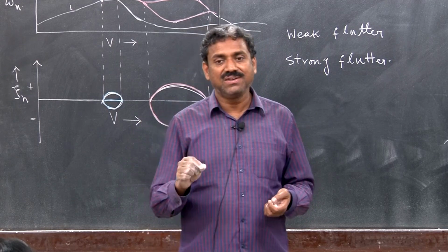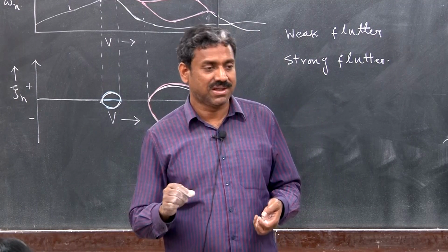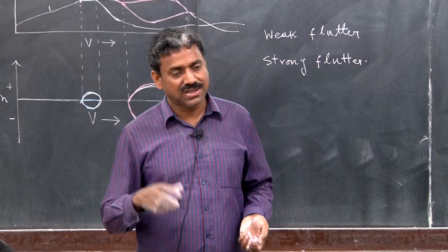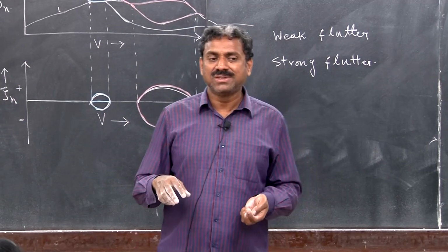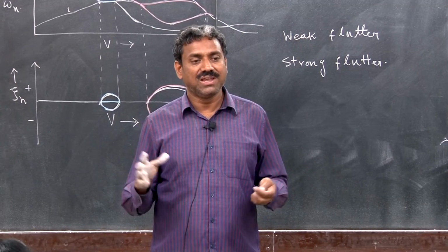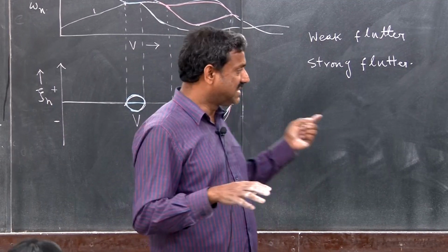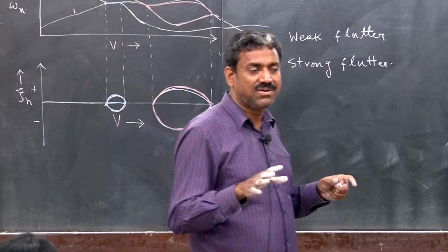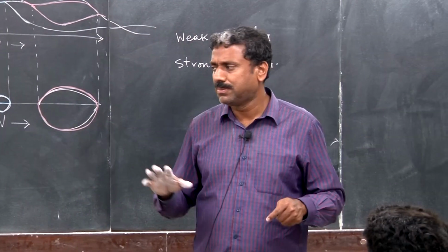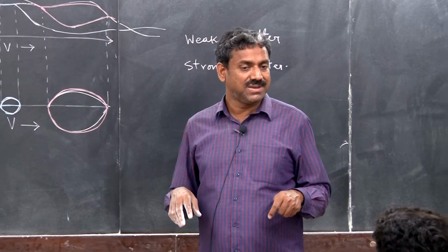And also you have to identify what is the critical load for the flutter, okay. Not only flutter, there are other kinds of things that happen also, which are called buffeting and galloping and other kinds of instability, okay. But please note that essentially these are the basic formalism for analysis of dynamic stability, okay.